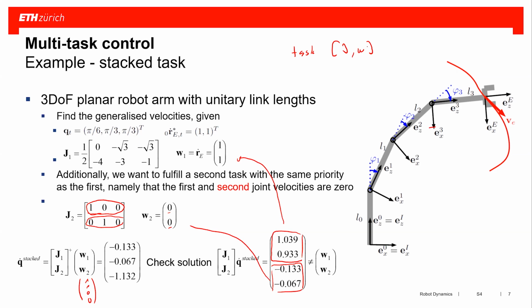It can be end effector velocities, R dots. It can be end effector angular rates. It can be joint level velocities. Anything that can be made up from Q dots through a linear multiplication. The J is nothing else than a mapping from one space to another space. So anything that relates through a Jacobian to a task description from the joint level description.